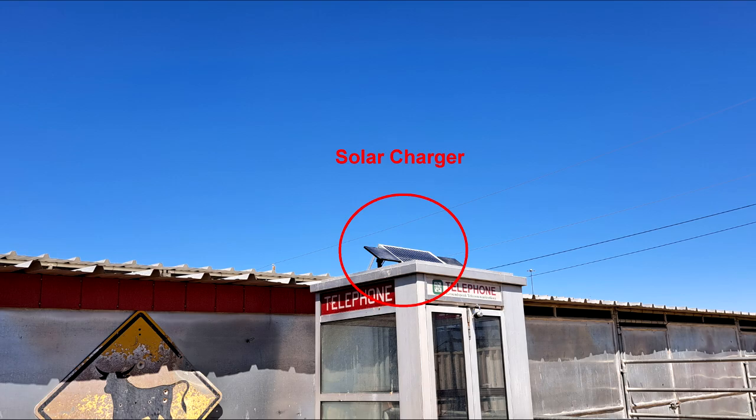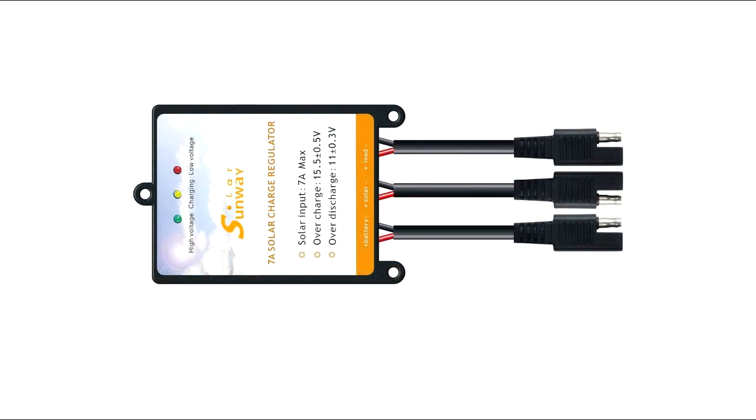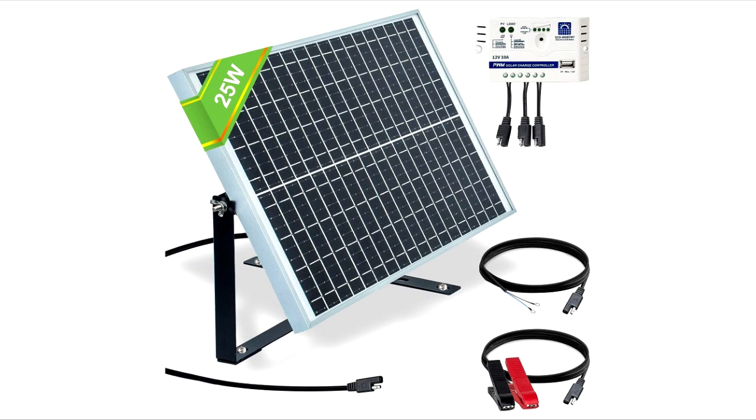These are available for trickle charging batteries and RVs, although you will only need a very small one. One rated at about 25 watts will be fine. The other part required is a charging regulator. Just like a line charger, if the battery is allowed to continuously charge at a high enough amperage, it will ruin it in a short amount of time. Starting around $50, there are kits available that include both the solar panel and the regulator. It does not need to be an expensive system. It only needs to trickle charge a 7-amp battery in a geocache.